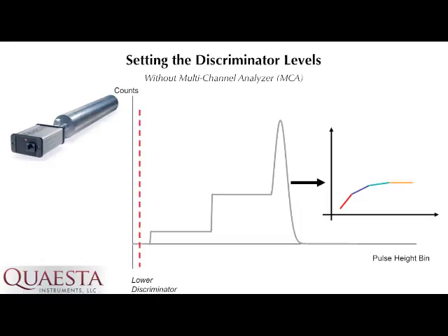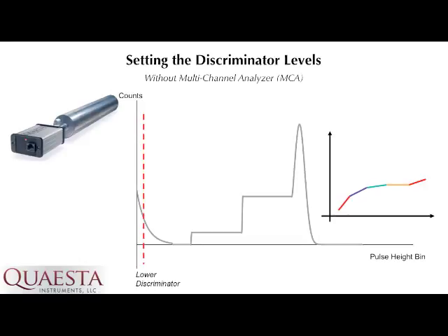Finally, when the valley region crosses the discriminator, there is no change in counting rate with increasing voltage, and the slope is flat for this region. Consequently, this region is traditionally called a counting plateau. If the spectrum is moved farther to the right, then the counting rate increases again, but the increase is caused by gamma ray events and low-level electronic noise.